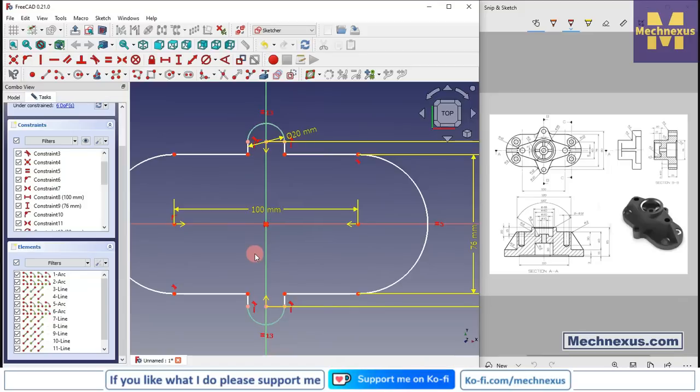And here constraint has gone, so we will select this and add a horizontal constraint. Select this and this and add a horizontal constraint. And here tangency has gone, so we will add a tangency.